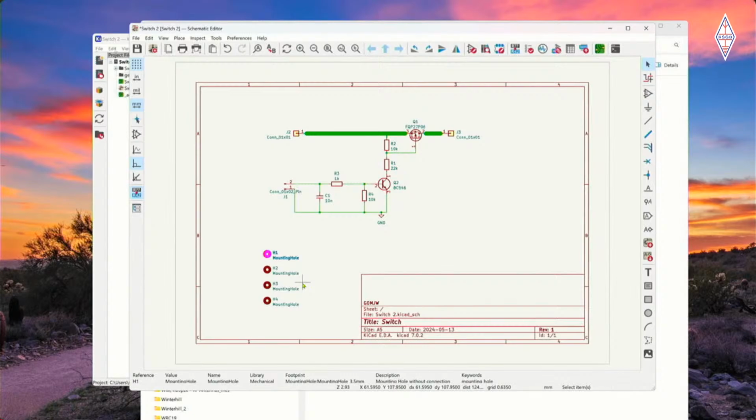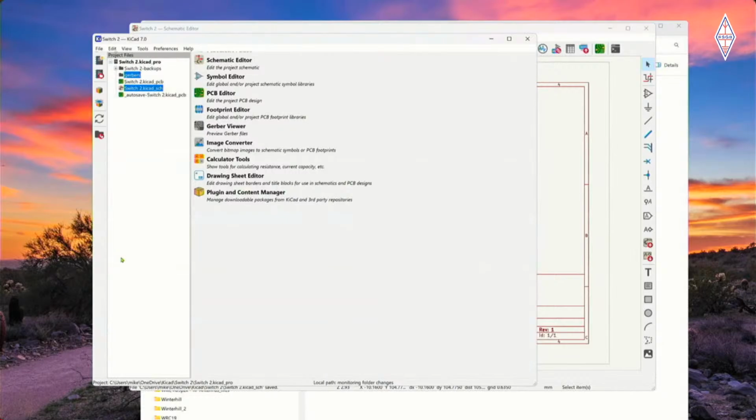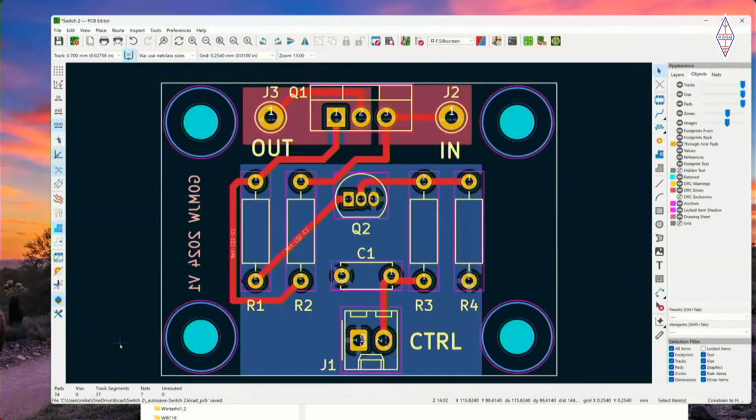But one other thing we didn't mention are the things called vias. And again, I think for maybe the average amateur who's not been in industry, they may wonder what a via is. Sometimes when we talked about this puzzle, I wonder if you could get that up, Mike, and do you mind demonstrating what this is? When you have a circuit board like this, it's like this puzzle that we talked about, but sometimes you just can't make the tracks all make up, can you? Because they have to cross over each other. Now, if they need to cross over, of course, you've got the other side of the circuit board. That means we've got to get to the other side of the circuit board, and we do that through a hole which doesn't have a component in it, and that hole is filled with copper, and that's called a via, VIA. So if you see that written somewhere and you wonder what it is, that's what it means.